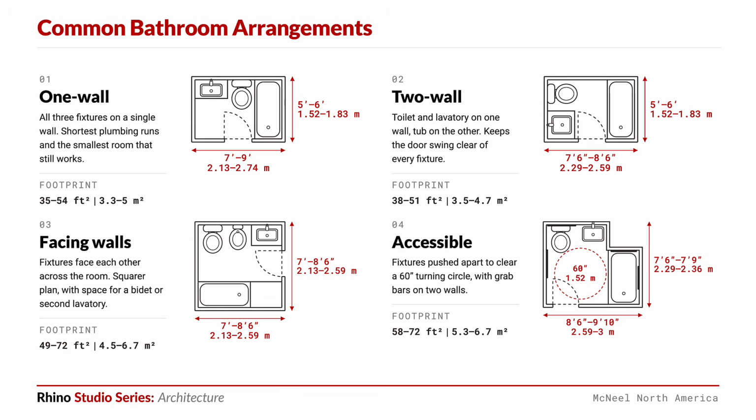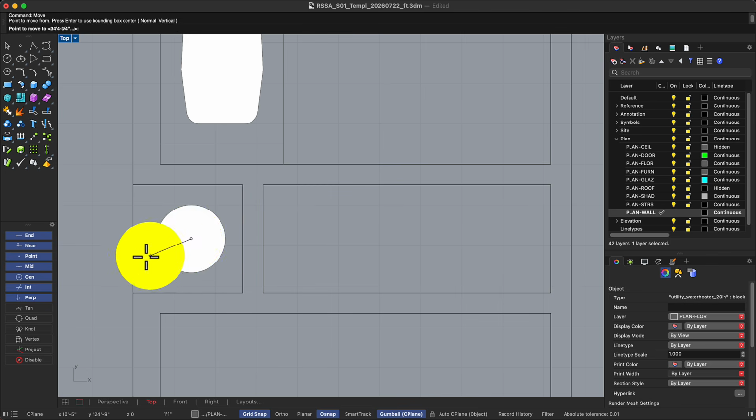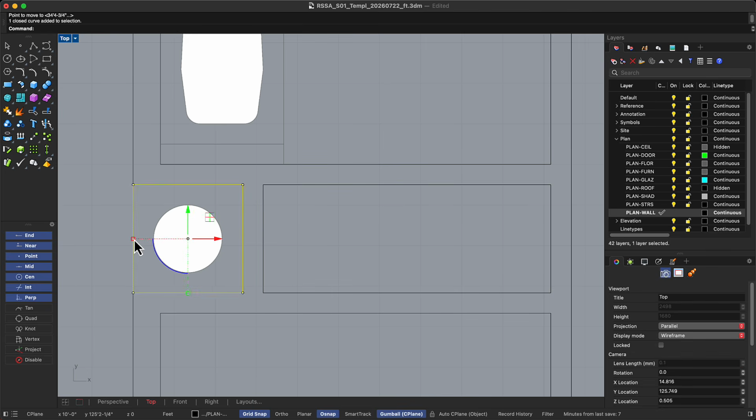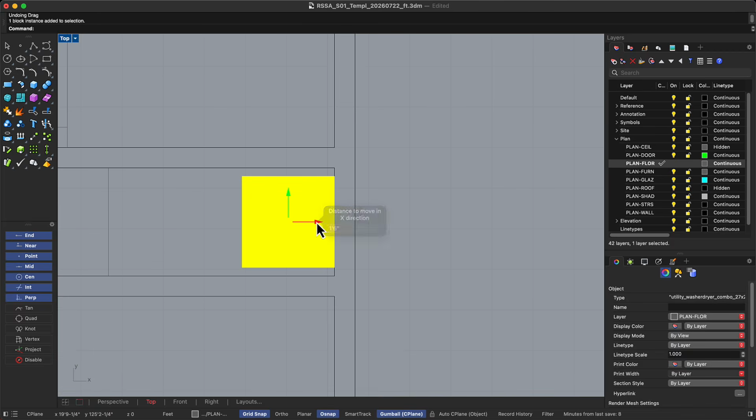Use the bathroom layout reference to compare compact arrangements for the toilet, lavatory, and tub or shower. Choose an option that maintains practical clearances and a door location that does not interfere with the fixtures. Keep the laundry and water heater near the service core when equipment requirements allow it. Grouping these functions reduces unnecessary long service runs and helps the compact plan work efficiently.